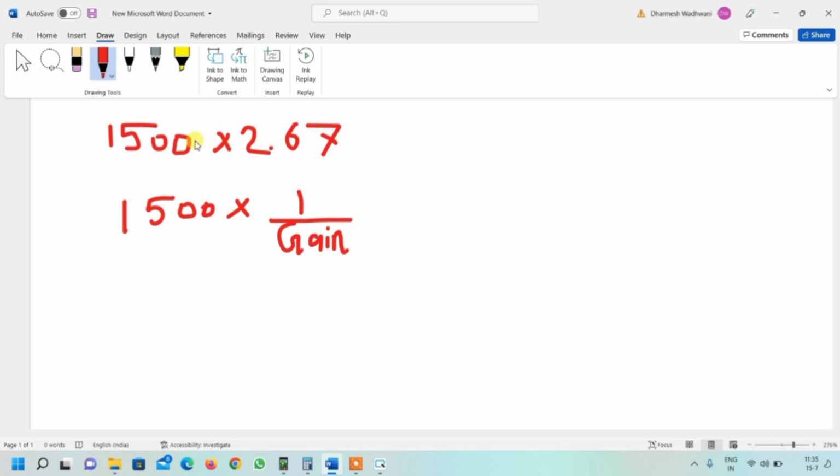As per the logic discussed in the first part of this topic, that is in the ladder diagram video, we have to get RPM from the user and then multiply by 2.67 because we want one decimal value to give to the analog output module. But here whatever we write in gain will be divided by RPM.